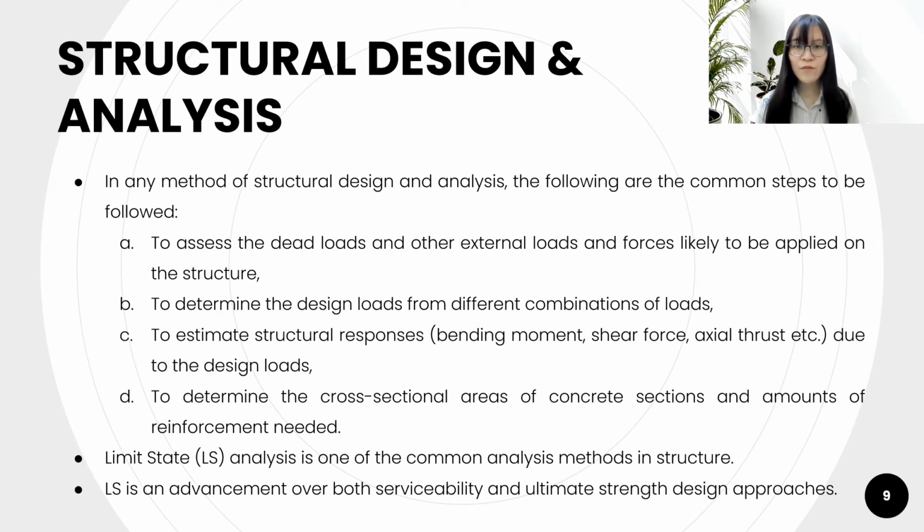Lastly, we have to determine the cross-sectional areas of concrete sections, and by using these cross-sectional areas, we can know the amounts of reinforcement needed. So in our case study, we choose the limit state analysis as it is one of the common analysis methods in structure. Limit state analysis uses more than one safety factor to provide adequate safety at ultimate load.